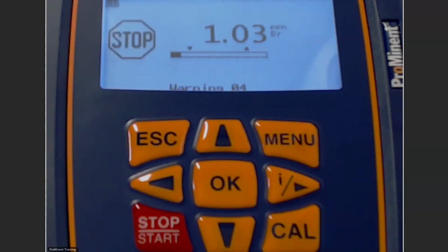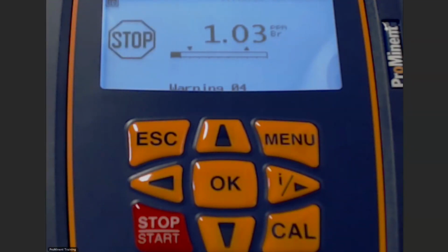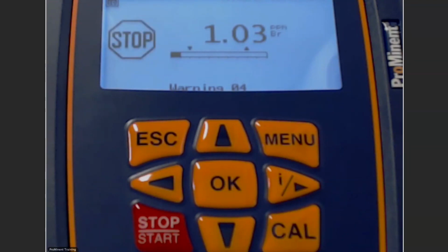As the pH increases, the HOCl changes to OCl minus. We can measure that with our CTE sensor. But the OCl minus is not as efficient a disinfectant as the HOCl. So it would be better for us to be measuring, and actually using in our system, HOCl.